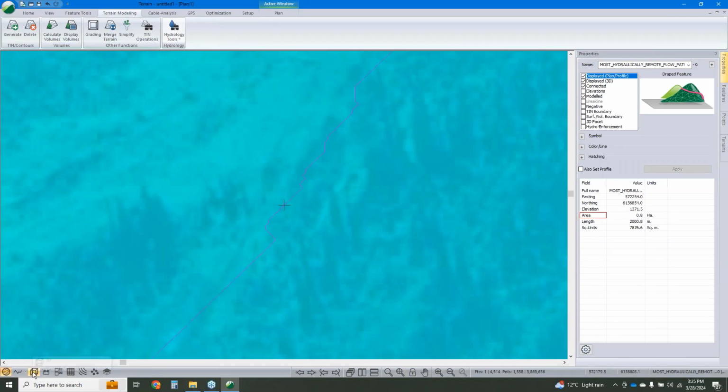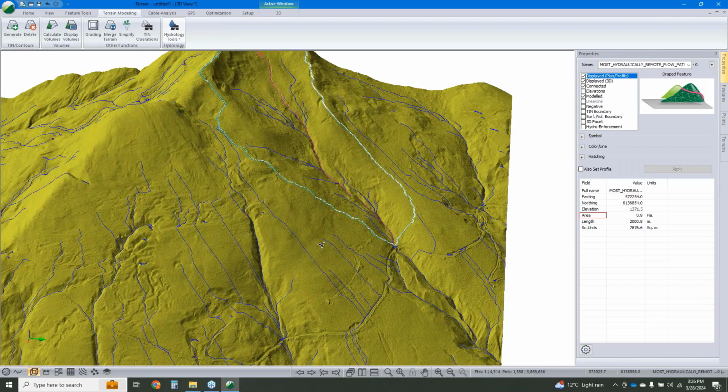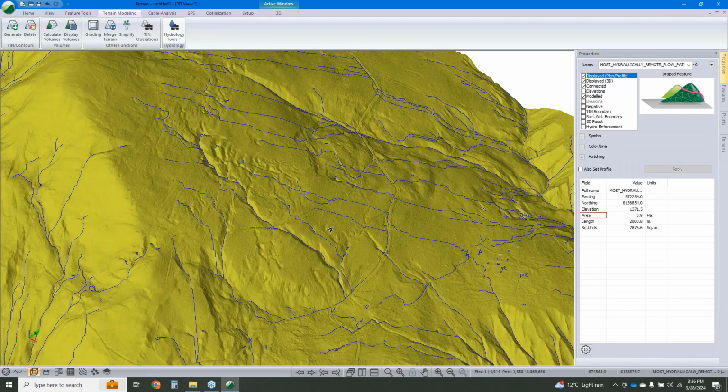And if we wanted to, we could cut sections across it and export that feature and the sections to something like HEC-RAS, in which case we can export a .geo file for that. So it's easy to do that more detailed analysis if needed, or if you're doing a river study. Yeah, so we've got our drainage area. Let's go over here and, oh, where should we do this?